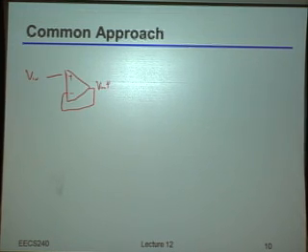So I just have something like this. Okay, so we've already said that if I'm not careful, I'm going to get things messed up with the loading. But it actually turns out that if I'm not careful, it's not even just the loading that will be messed up, it's actually even the DC bias that will get messed up. Okay? So whatever we do, we're going to have to do very carefully to try and fix both of those problems. All right?